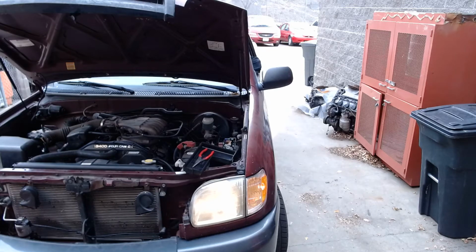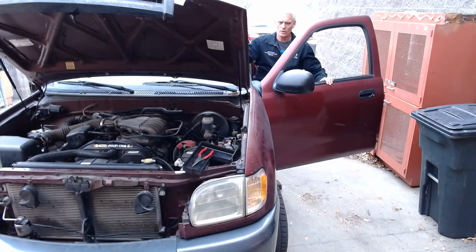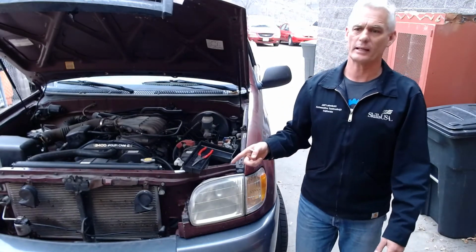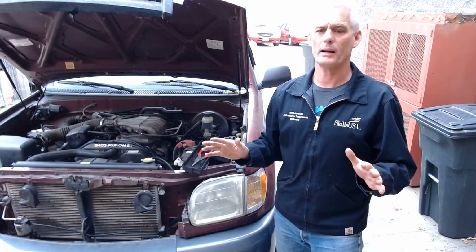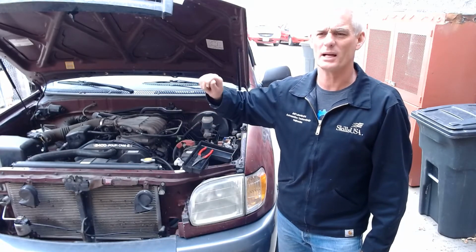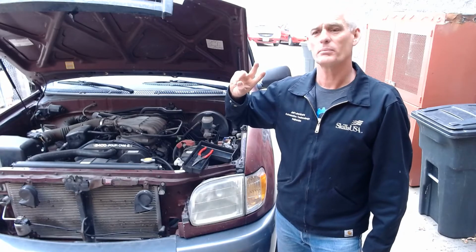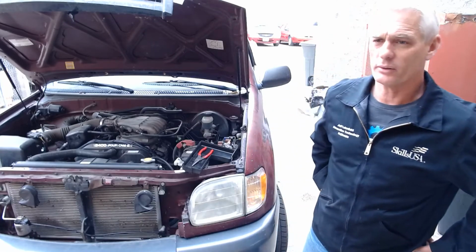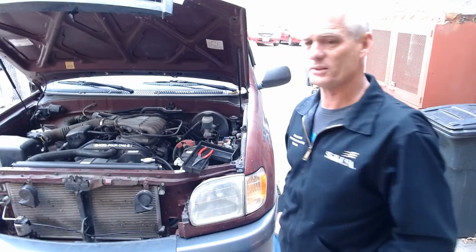Okay, so this is like a classic scenario where the headlights are not dimming. So you're thinking, okay, it's not trying to pull power from the starter, but you can hear the audible click, one click, and you heard it multiple times because I was going like this. The pinion gear is being pushed out into the flywheel, but it's not spinning the starter. So pretty much likely it's the contacts in the starter solenoid or the brushes inside the starter, but it's probably a starter situation. Here's how we're going to diagnose it further.